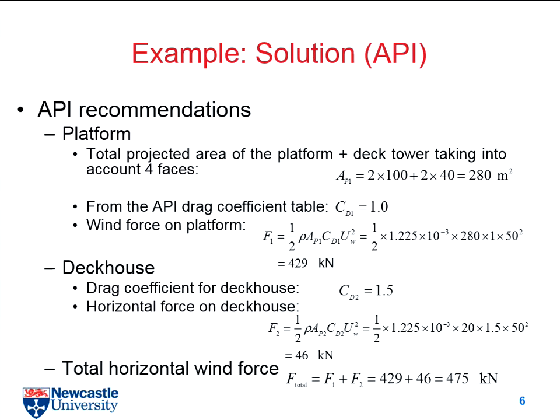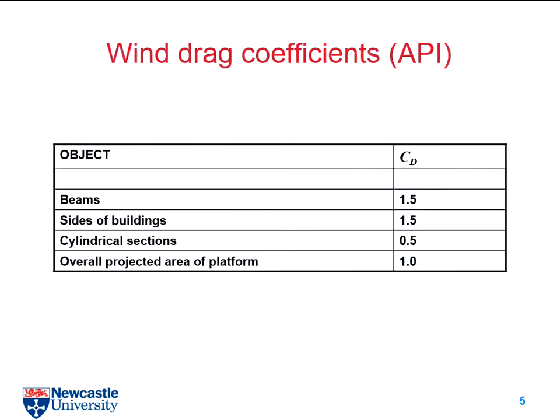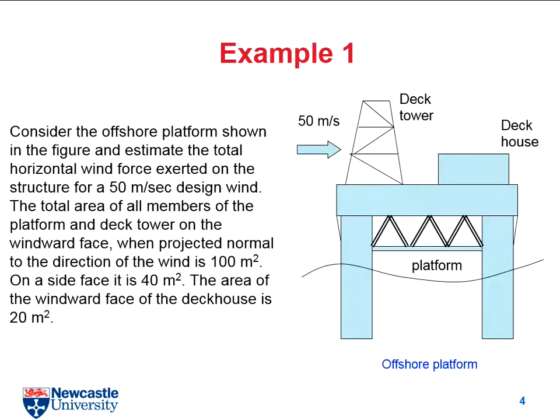So that's the reason why we just use 20 for the acting area. It's the face area, right? If you go back to the equation, the face area of that house is here. And because it's not a porous structure, we will not generate a lot of turbulence like the other structures. It means we don't need to care about the turbulence acting on the side surface. That's the reason why we just use 20 as the acting surface.